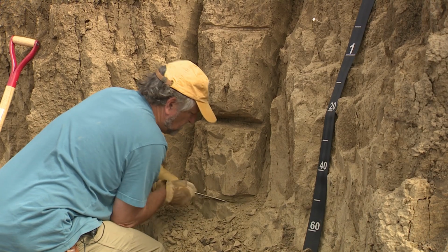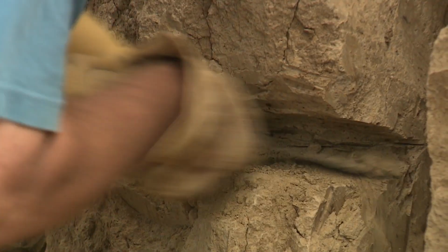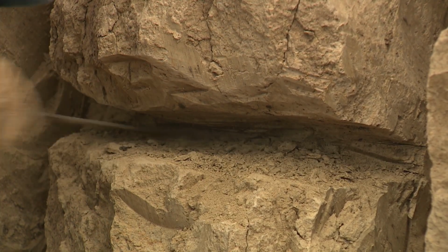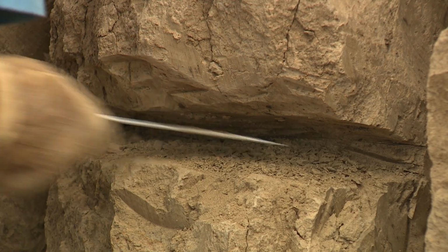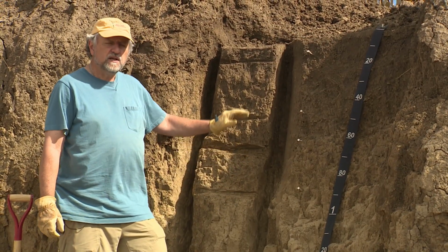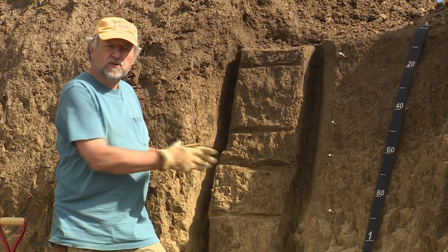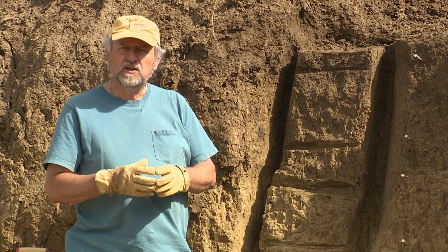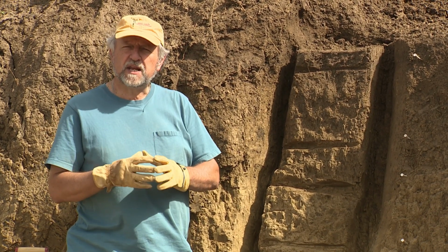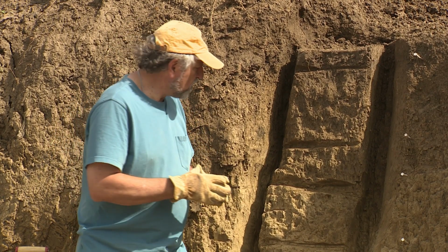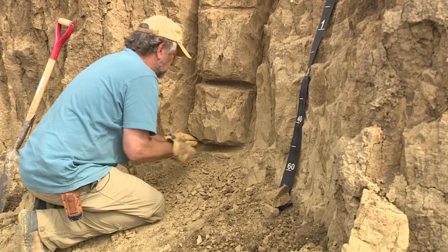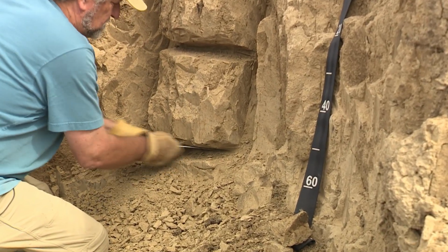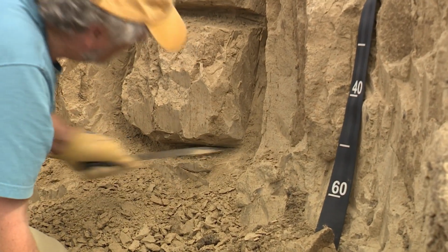But the main point is that these are horizon-centric sampling efforts. So what we're going to do in a moment is carve out these chunks that are based on horizons, and we're going to then shear off those larger blocks, and from those blocks break out intact clods of an appropriate size, which will then be processed for shipping and handling. So how we're going to do that is use some sort of a carving knife or shovel to extract these deep grooves on either side.